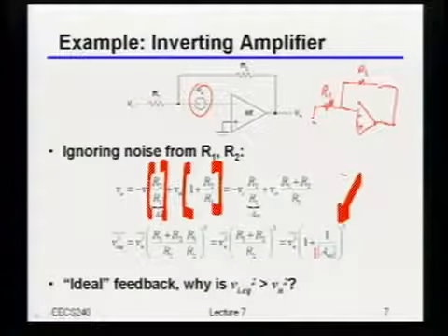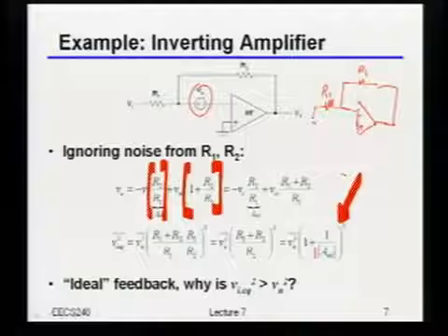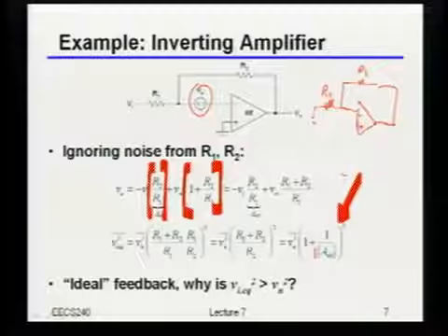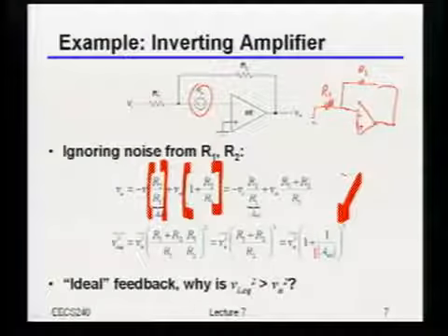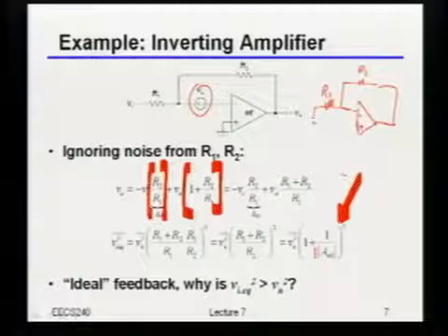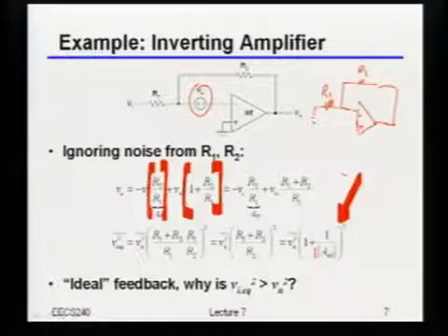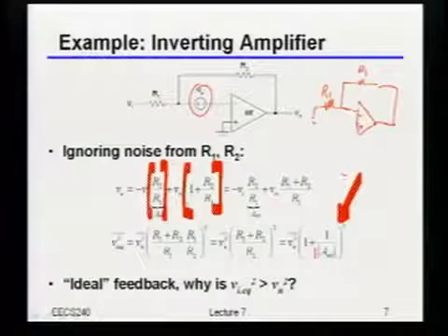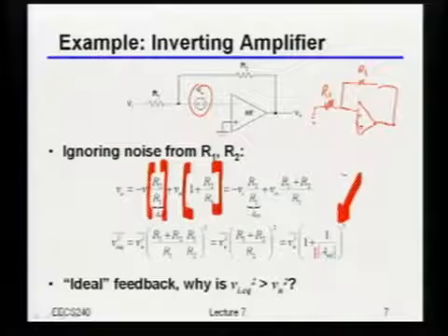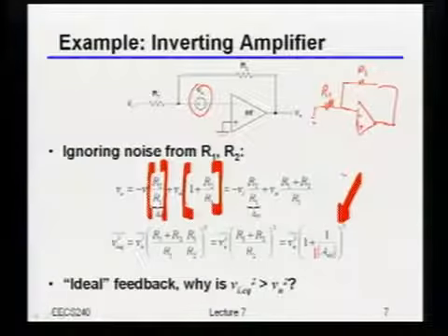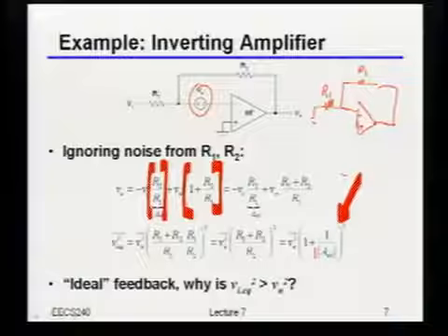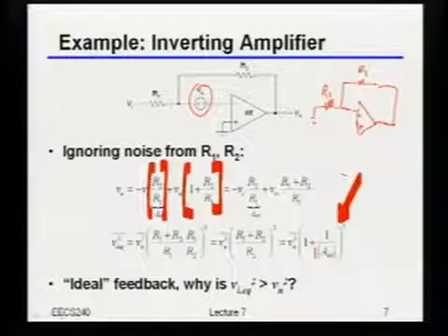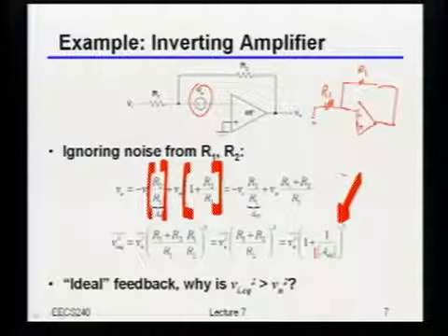Like you said, you used the wrong topology. Okay, well, I used the wrong topology, but still, I have perfectly ideal resistors and everything here, right? So this is kind of weird, because I didn't add any noise from the resistors. So you're kind of right, by the way. It is actually the wrong topology, but specifically, what's wrong about this topology? There's no cancellation resistor on the non-inverting input. What do you mean cancellation resistor? Can you make the two cancel? Unfortunately, I don't think so, because if I added another resistor, especially if it's non-ideal, it's going to mess things up.